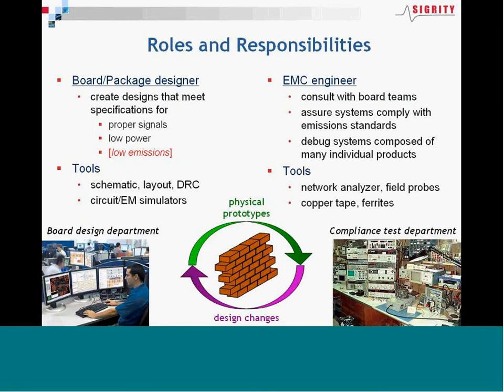There are different roles and responsibilities between board designers and package designers. On the left side is the target audience, where we're creating designs that meet specifications for proper signaling, for low power, and maybe to some extent in the past for low emissions. Typically, an EMC engineer, whose roles and responsibilities are on the right, would be a consultant, and his role would be to provide design guidelines that help the board layout engineers do the proper capacitor placement and maybe power delivery plane shapes. The tools used by board designers are schematic, layout and DRC, and to some extent circuit simulation and even EM simulation tools.